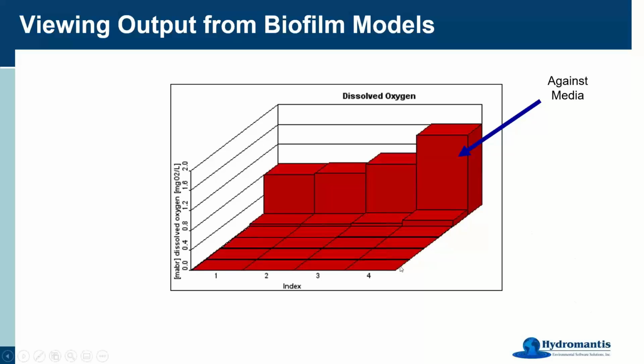So as we go from left to right and we go downstream, you can see the oxygen was increasing here, which is maybe not too surprising. That would be the same as if you were to provide an equivalent amount of airflow to a plug flow tank. At the front end is where most of the loading is going to be, so you're going to have a little bit less residual oxygen there. But as the substrate and ammonia get used up, you're going to have a little bit of oxygen leftover, more so at the end of the system. We can see it's even bleeding through to the second layer here a little bit too.